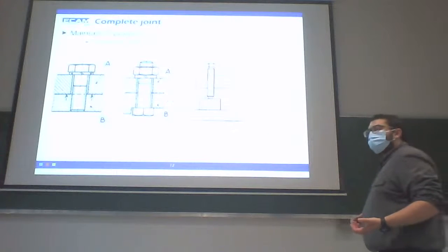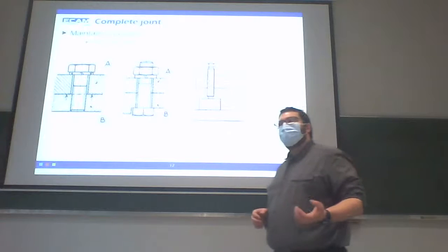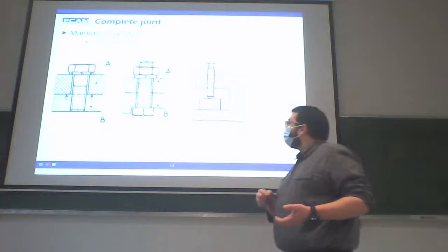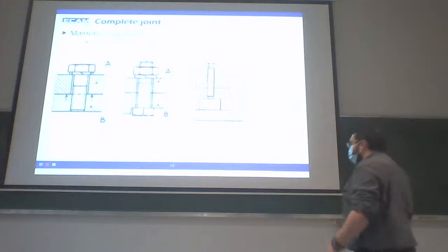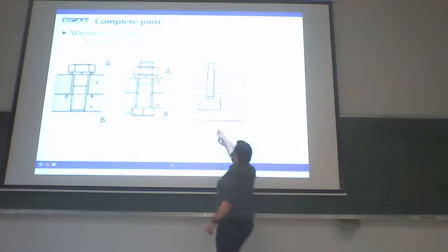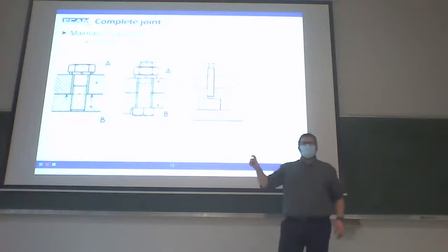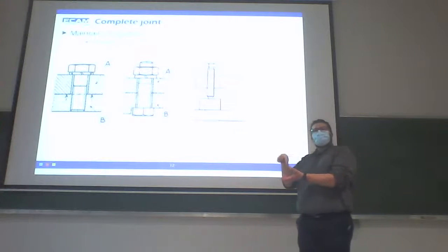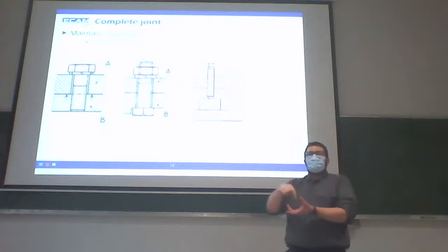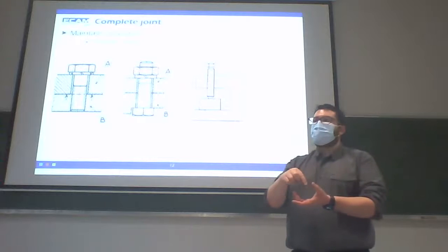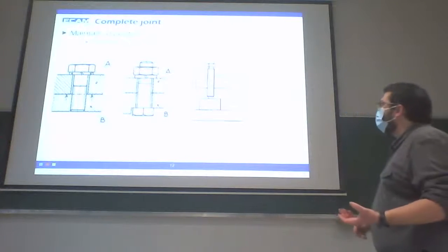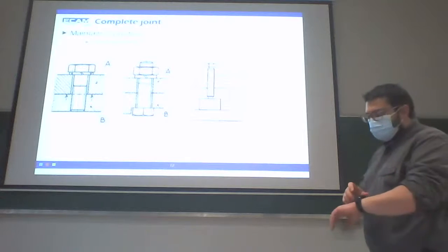Or we can use a screw or threaded element to realize the pressure between the two parts. Here we'll fix this part in the middle, inside the C-shaped part. And we'll use the pressure screw to add an effort between the two parts and to fix the position of them, to maintain the position between the two parts.